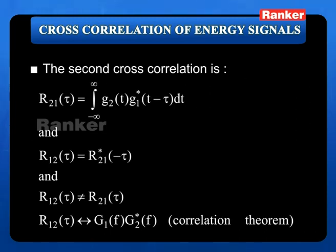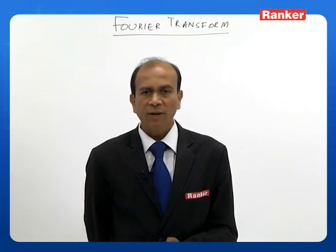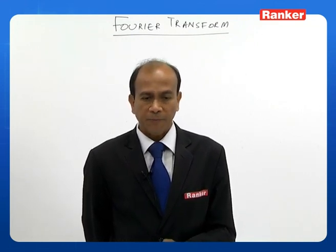Now, when I have R12, I can also have R21 of tau. R21 of tau is equal to the integral from minus infinity to plus infinity of g2 of t g1 star of t minus tau dt. R12 of tau is equal to R21 star of minus tau. And generally, R12 of tau is not equal to R21 of tau.